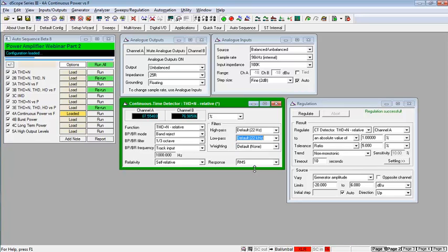However, what we're doing here is at high frequencies. Let's take, for example, 15 kHz. At 15 kHz, all of the distortion energy, second harmonic, third harmonic, and everything else, occurs from 30 kHz upwards. So in this case, that's beyond the upper limit of my measurement filter here.